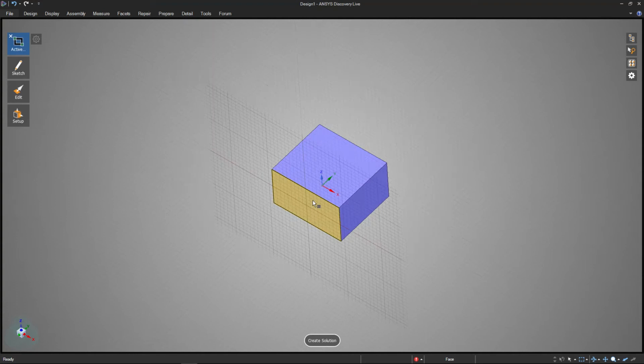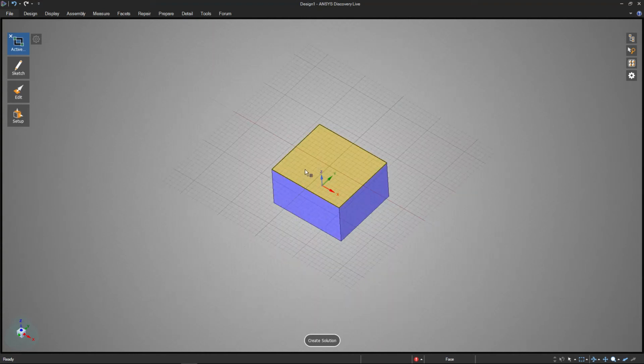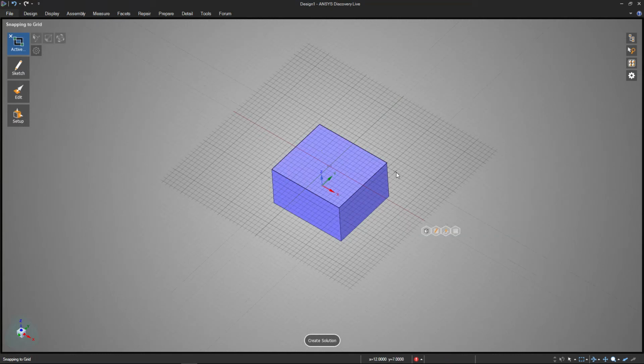When you first click a sketching tool, the first click that you make is not actually going to be drawing that rectangle. It's going to be selecting what plane you want to sketch on. A lot of people forget that this is an important first step. I'm just going to draw on the top right now, so that's my first click. Now with the plane defined, the tool is actually the rectangle tool. I'm just going to make a miscellaneous rectangle somewhere in the middle and then hit escape to get out of that draw tool.